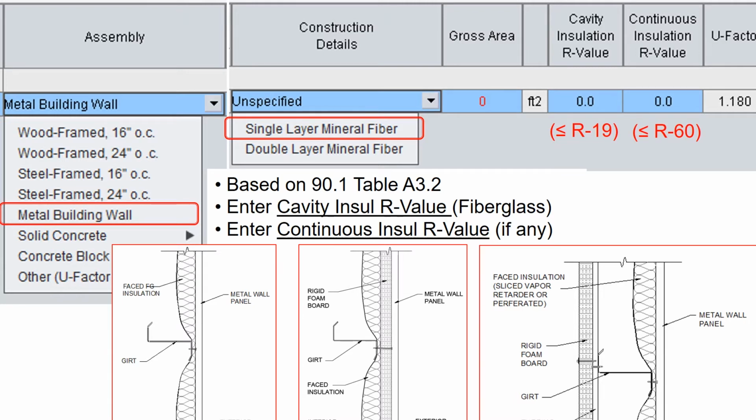Other options could be spray foam, could be insulated metal panels. I can't think of any other options, but if you have another option where the R value remains consistent over the framing members or in and around the framing members, as long as it has a consistent R value to avoid thermal bridging, you could use that.